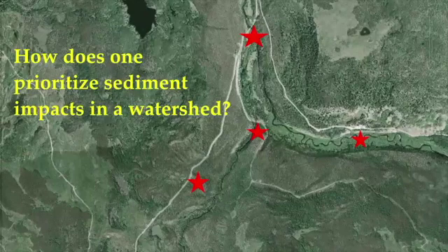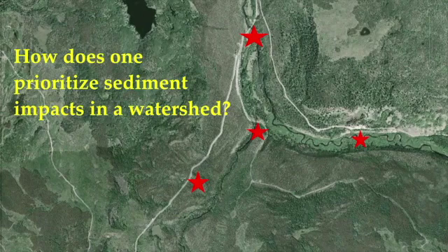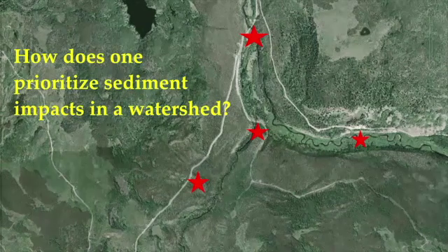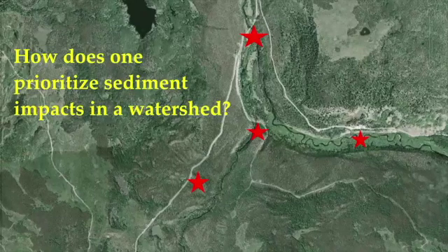Finally, once you have done an assessment of several sites within a landscape, from those assessments you can ask yourself, where can we make a difference? Where can we make an improvement to the water quality of a site with a high level of fine sediment generation? There may be issues associated with grader berms. There may be issues with a misplaced culvert, or a bridge built with a deck below grade so that water runs onto the bridge rather than away from it. There can be many different types of problems. Some will be easy and inexpensive to overcome, and others will be very expensive or even not possible to change.